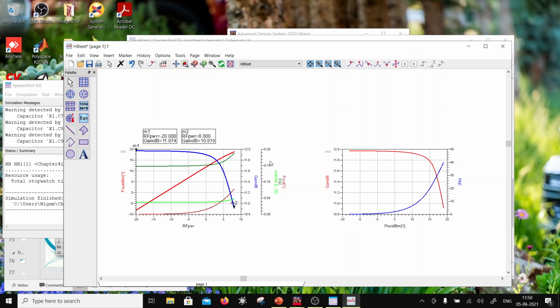And this is with respect to a certain quiescent current, and quiescent current is very much restricted because the current gain is going to be infinite, right? So basically the quiescent current is setting up the output power in case of a FET. So this is the basic difference between a FET and an HBT or a BJT.